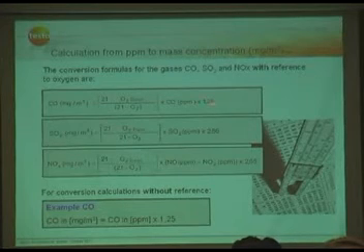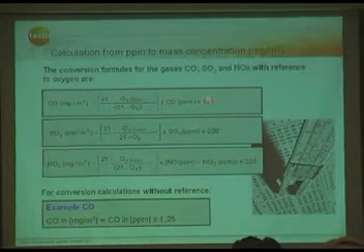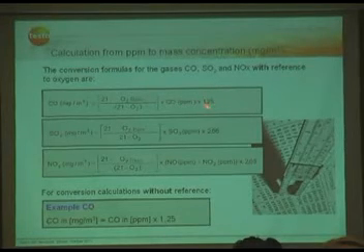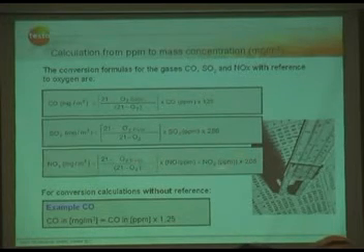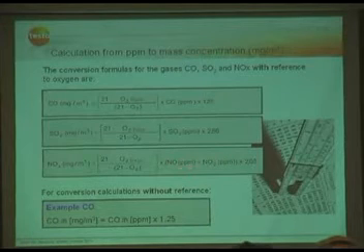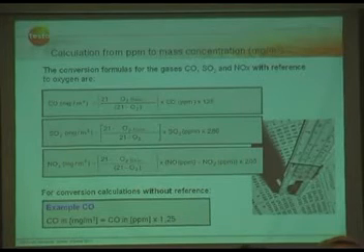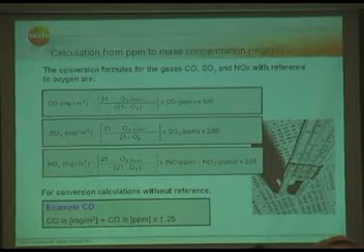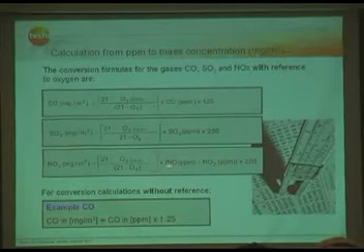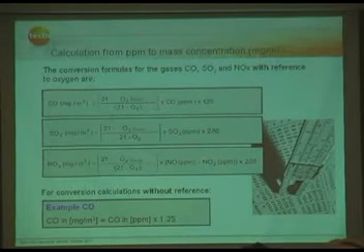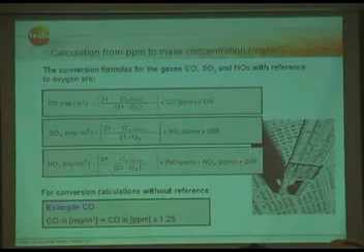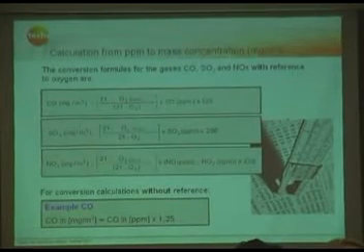And here you can see each gas has a specific density at norm conditions, like CO is 1.25, SO2 is 2.86, and NO2 is very specific, because here we add both values, NO and NO2, but for the density only the NO2 value is being used, because at the end of the stack, most of the NO reacts with the present oxygen of excess air, and at the end of the stack you have 90–95% NO2 left. This is why the density of NO2 is being used for this calculation.